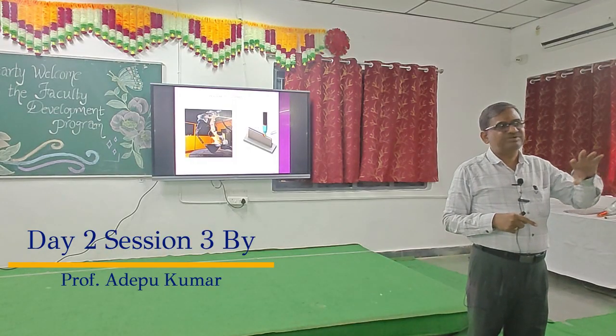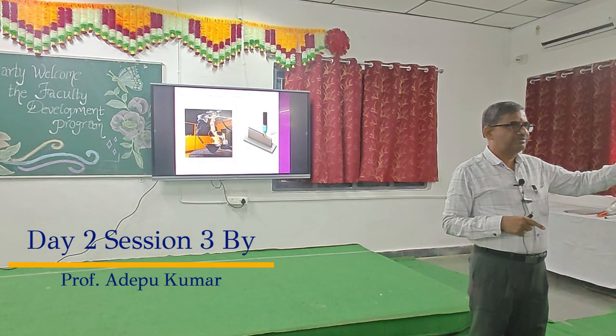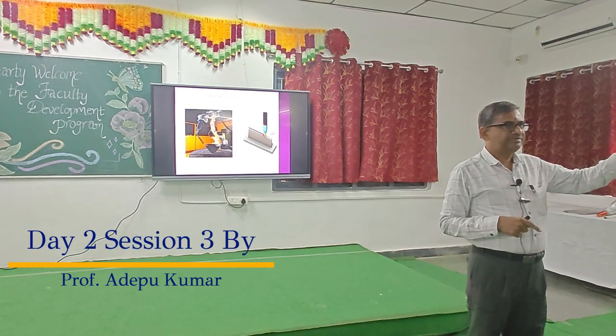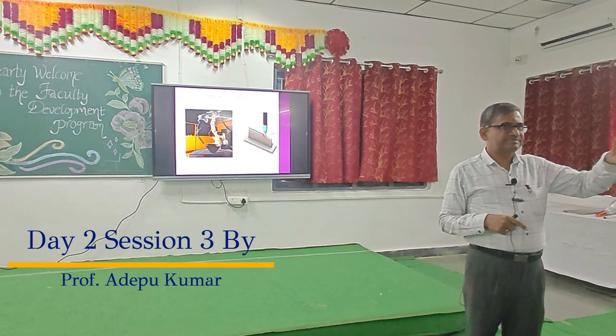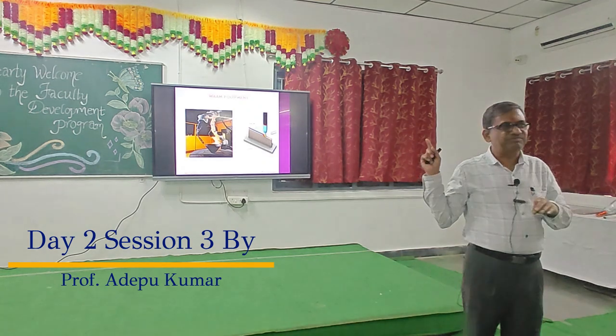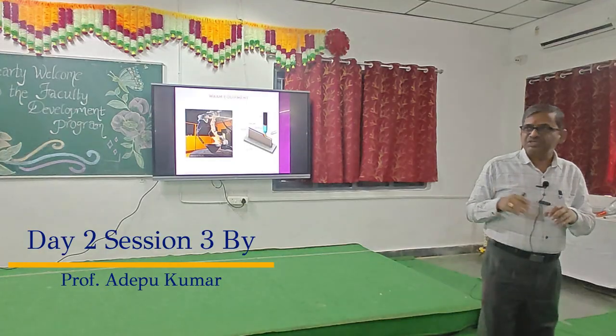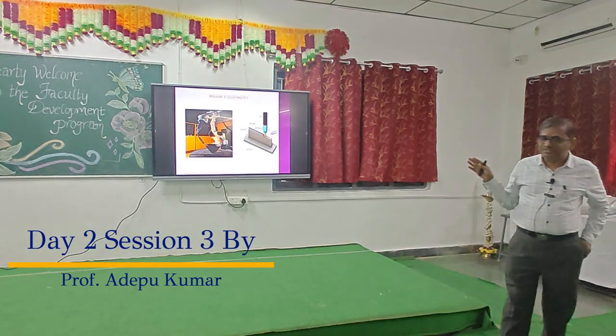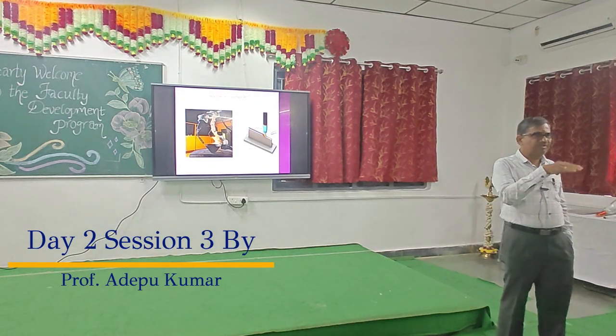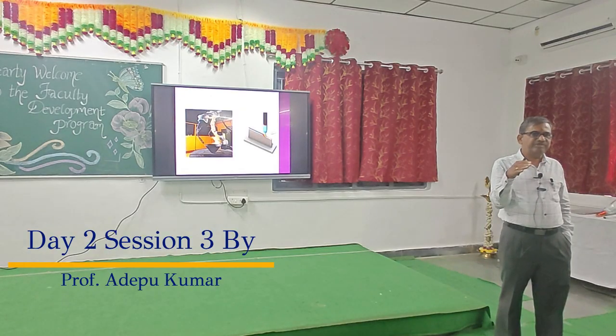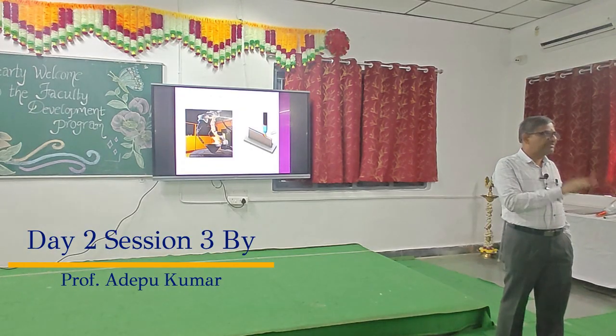They will generate only the path planning of a robot. That is enough. So the path planning you get as per your CAD file, then you are able to generate the components. This is the latest trend in wire arc additive manufacturing, because developing the path planning for complex geometries is very difficult.